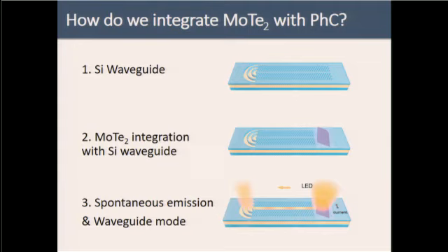What we could do is, as we flow a current through the p-n junction, the device is a light emitting diode. It's so simple. And the emitted light could evanescently couple to the waveguide. And at the other end, the destination, let's say, we have a graphene coupler. We can couple it to our microscope, our detector, and we can see them. So this is basically the idea that we want to demonstrate, that this light emitter is working.